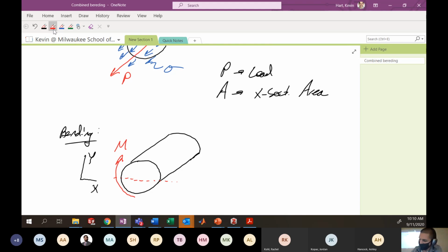All right, where this M here is tending to provide a rotation about the x-axis, so we would label this as Mx. It's trying to bend the bar upwards in this particular situation. You may also see it represented with a double arrow in the direction of the bending moment. You can think of the right-hand rule, curling your hand. If you thought about the right-hand rule and bending this particular bar with this Mx moment, your thumb is indicating about which axis the moment is being produced. In that case, this would be about the negative x-axis, because by the right-hand rule, my thumb would be sticking to the left if I'm looking at this picture.